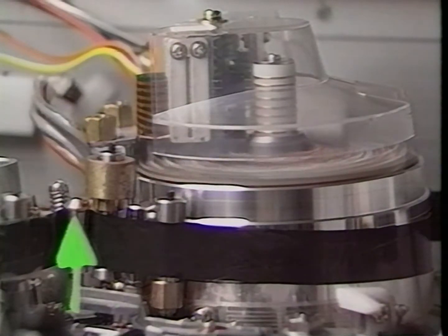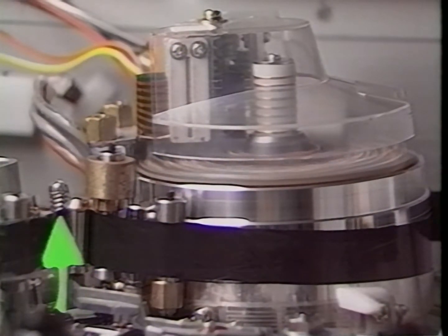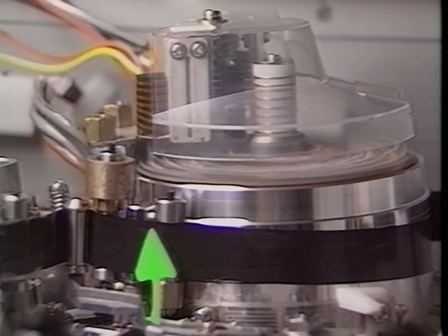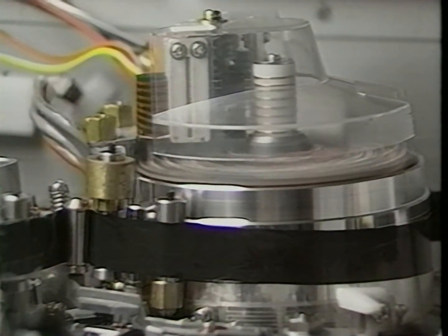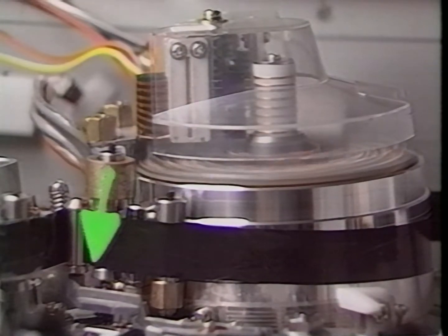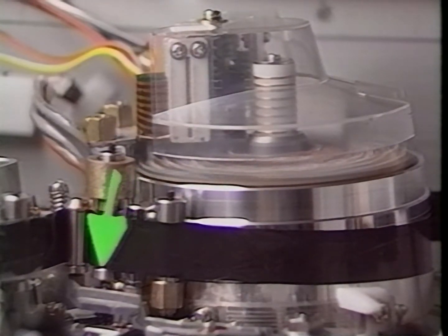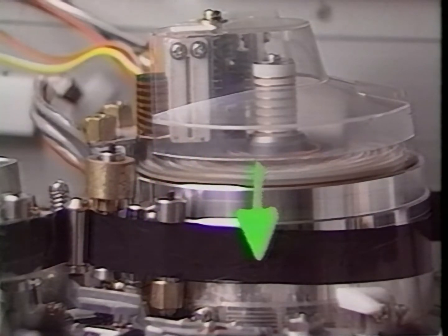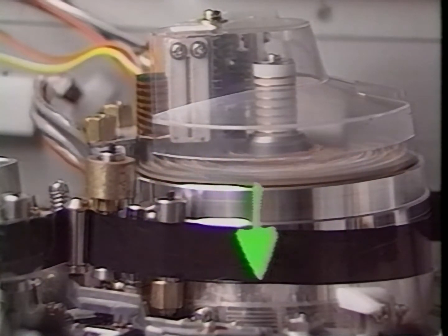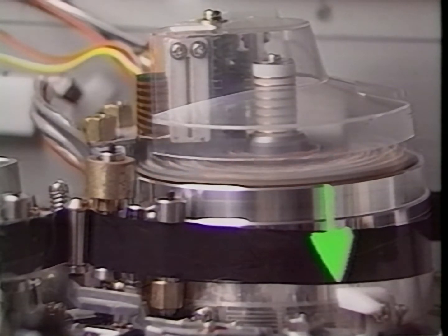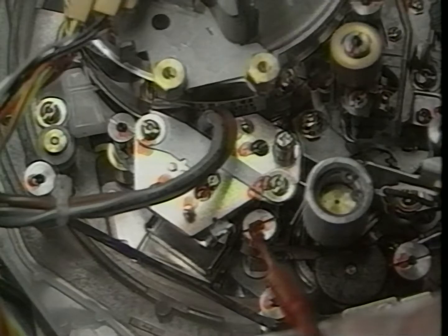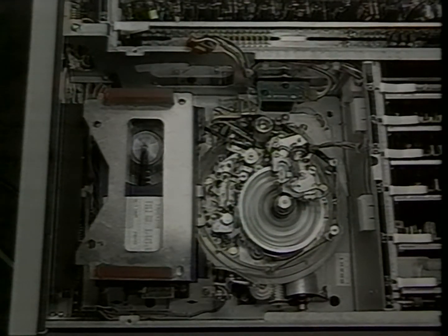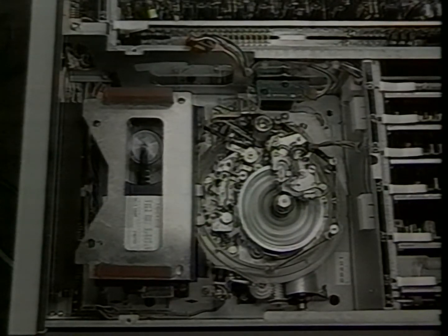On the entrance side, the upper edge of tape is controlled by the upper flanges of the tension regulator and tape guide 2. Tape guide 1 and the rabbit guide control the lower edge of the tape. And so the tape is fed accurately to the scanner. On the exit side, the upper edge is controlled by tape guide 3 and tape guide 4 controls the lower. The tape then continues past the capstan and returns to the take-up reel.